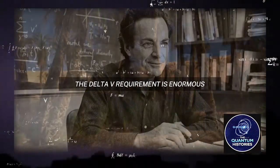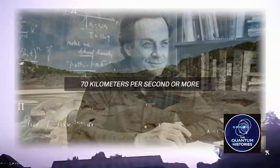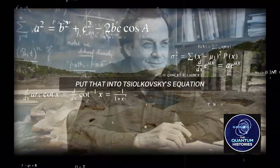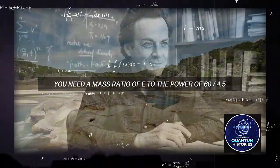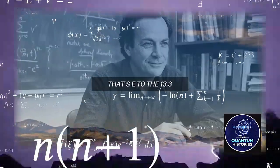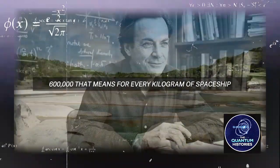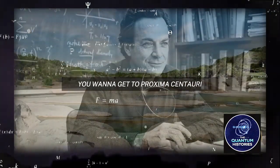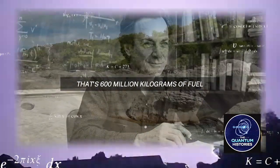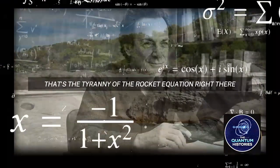The delta V requirement is enormous. We're talking about something like 50, 60, 70 kilometers per second or more, depending on exactly how you do the mission. Let's say 60 kilometers per second. Put that into Tsiolkovsky's equation. You need a mass ratio of e to the power of 60 divided by 4.5. That's e to the 13.3. Do you know what e to the 13.3 is? That's about 600,000. That means for every kilogram of spaceship you want to get to Proxima Centauri, you need 600,000 kilograms of fuel. That's 600 million kilograms of fuel for a 1-ton spacecraft. That's insane. That's the tyranny of the rocket equation right there.